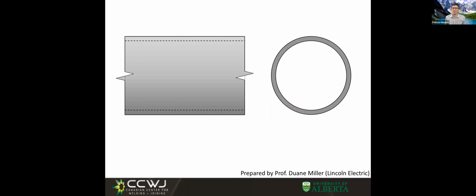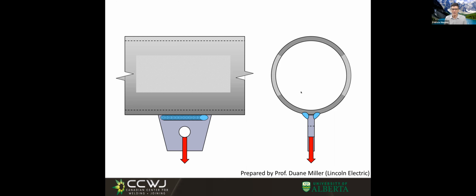Okay, an interesting one. Let's put a load-bearing plate on a pipe. Okay, good or bad? What do you think? Good or bad? Bad, horrible. Yeah, thank you, Eddie. If you pull here, what's going to happen? I pull the load, the part that is taking care, the stiff part of the pipe is the vertical part, right? This is not really a sharp line, but the vertical part of the pipe is the one that is stiff and is the one bearing the load.